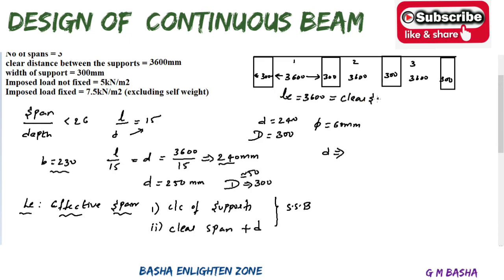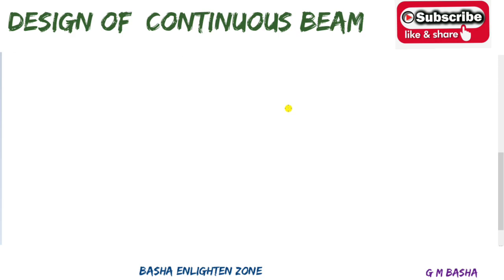But if you are getting the point, if BW will be less than L by 12, for example, it will be 300 means your width of the support will be around some 280. At that time you can choose it like a simply supported beam. But here both are equal, therefore we are choosing the first condition. Clear span is the effective span according to our condition. Then the next step is check with the loads.